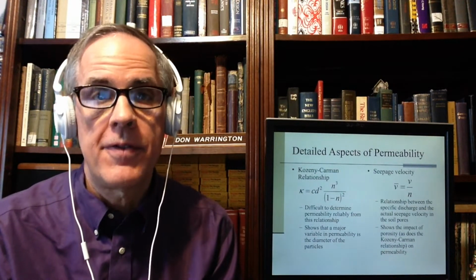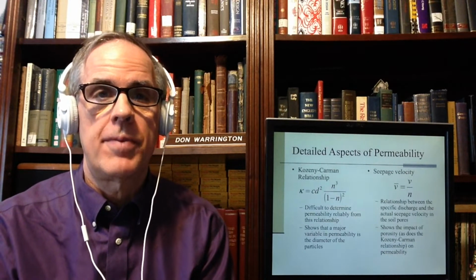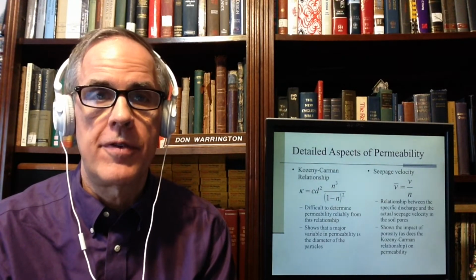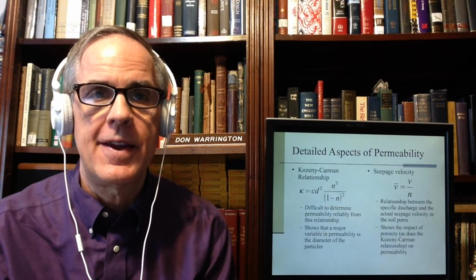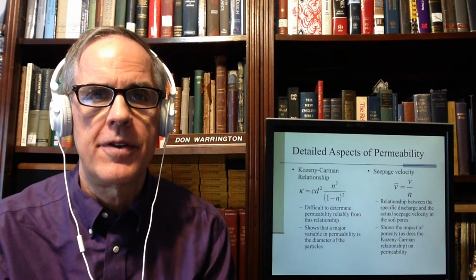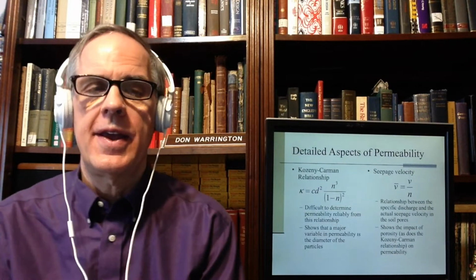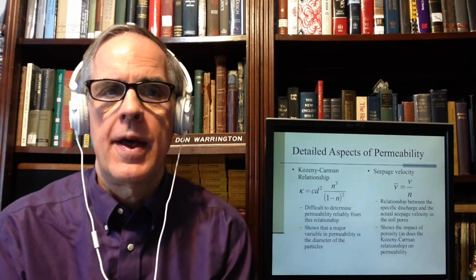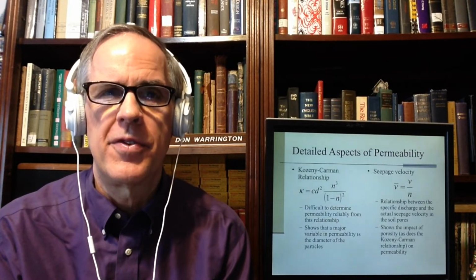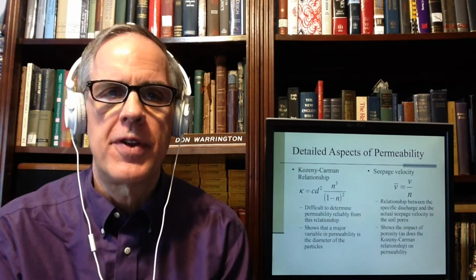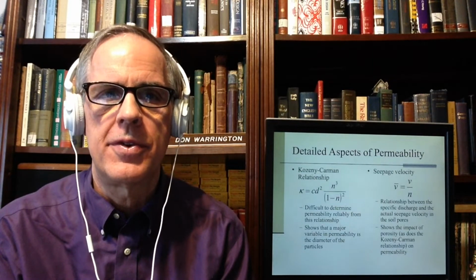We also have the seepage velocity, which basically takes the specific discharge and divides it by the porosity. I mentioned earlier that it's sometimes difficult to get a handle on the actual velocity of the fluid flowing through. The seepage velocity is an attempt to do that on a fairly simplistic level.